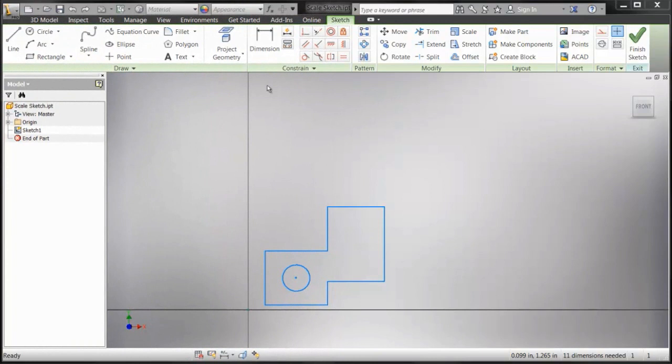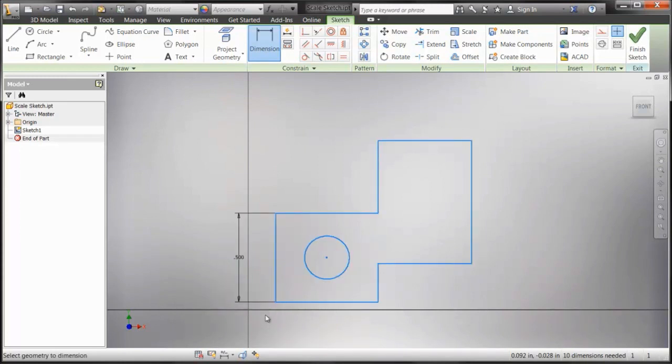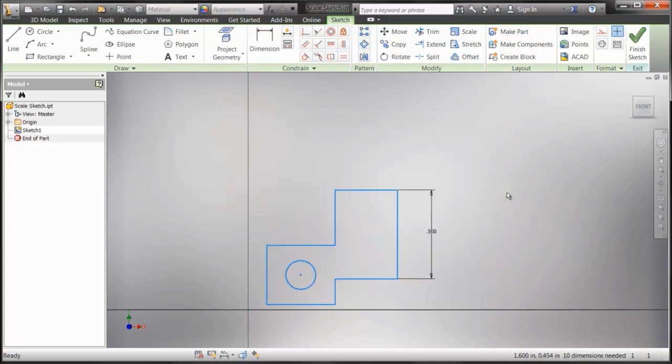Another new modification is the ability to scale the sketch based upon the first dimension. When I place this, it will scale up, since the initial dimension was larger than the placed one. If I add another dimension, it will have no bearing on whether or not this geometry is scaled up or down. However, if I delete the first dimension placed, and there's only one dimension on the sketch, that dimension then controls how big or small the resulting sketch becomes.